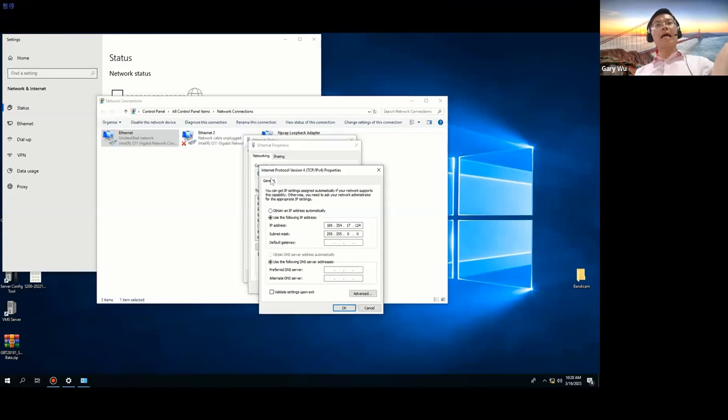The next step is the IP address settings. Here we use the following IP address, which should be a non-used IP address within the same IP address segment as the camera, the IPS 1800 or the IMA 800. The IP address, subnet mask, and default gateway are mandatory, and DNS is optional.